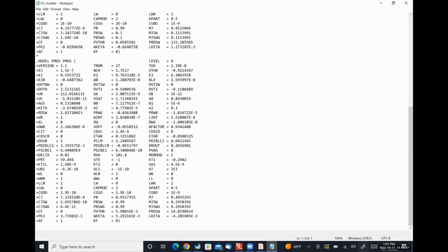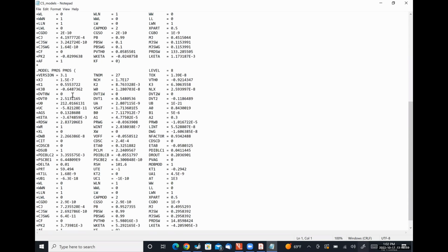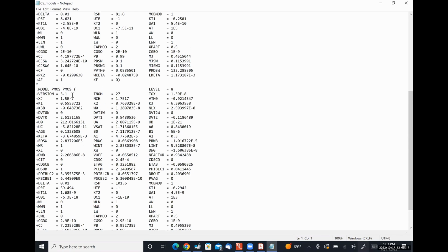And then if we scroll down to the PMOS device, we have something pretty similar. We have a threshold voltage of negative 0.92. So that's a pretty big mismatch, really 670 millivolts to 920 millivolts. That's a pretty substantial difference between the two things. Our hole mobility, if the mu naught does represent a hole mobility here, which again, I'm not 100% sure. That's why we're going to extract it from a simulation. 212 would be roughly half of the other one, which means in our